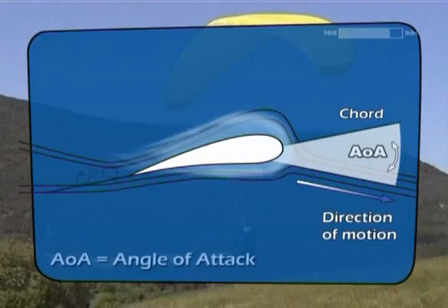Being aware of the stall is very important when learning to fly, since inadvertent stalls are very dangerous and should be avoided. Always keep your hands high and make sure you feel good airspeed on your face whilst flying to avoid the stall. Only when making the landing flare should you use deep brake inputs.